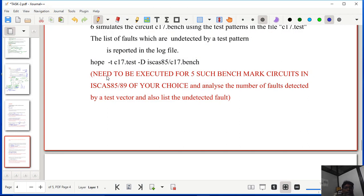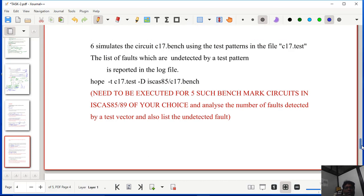So what it does is, this particular task needs to be done for 5 different benchmark circuits and you analyze the number of faults detected by the test vector. One important thing you can notice is that Hope will generate a log file. So you can go and open that log file and see what the undetected faults are. Let me see for this particular